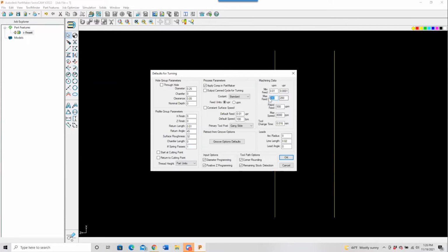But we also use a maximum feed rate when we can't use G0 on the machine. If you're working in a mill end polar condition, in polar motion, most controllers will not accept the G0 while we're in a G12.1 command, which is the polar command. So how do we get around the rapid? We put out what we call a fast feed. There's an actual variable in the post called fast feed. So once my G12.1 kicks in, instead of a G0, I'll see a G1 for a feed rate, and the feed rate is going to be whatever I set this to. And I can mimic a rapid rate.